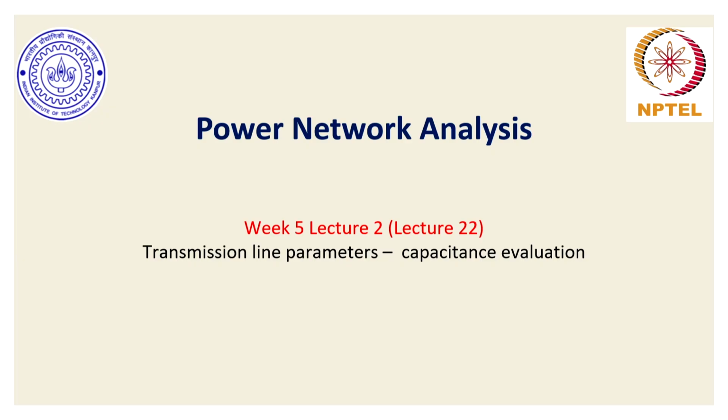In the previous few lectures, particular to module 4, which covers the topic of transmission line parameter evaluation, we have discussed what is resistance, what is inductance, how we evaluate physically the values of resistance, be it DC resistance or AC resistance, what is skin effect, what is corona loss, and how you evaluate the inductance using magnetic flux linkages. So we'll continue with a similar discussion and understand how line capacitance can be evaluated for given three-phase transmission lines.